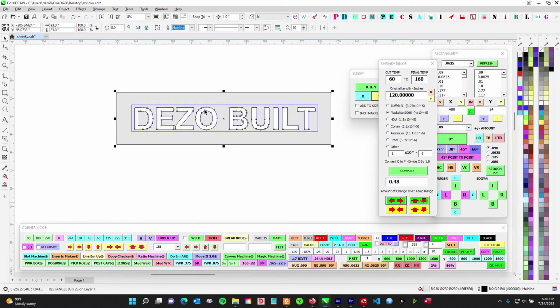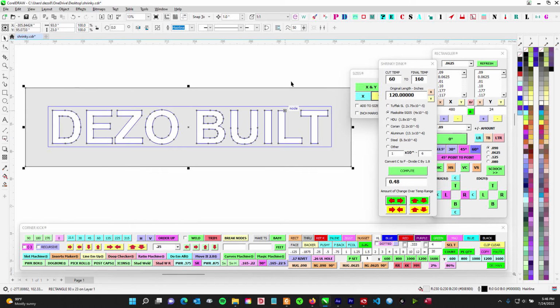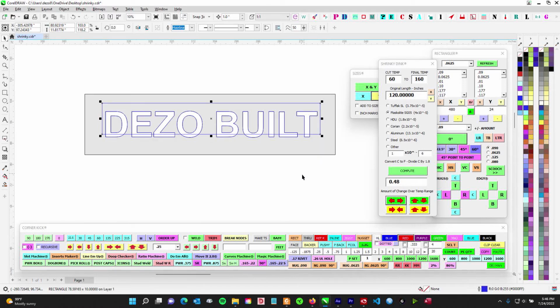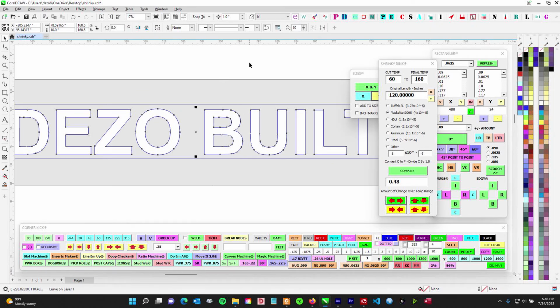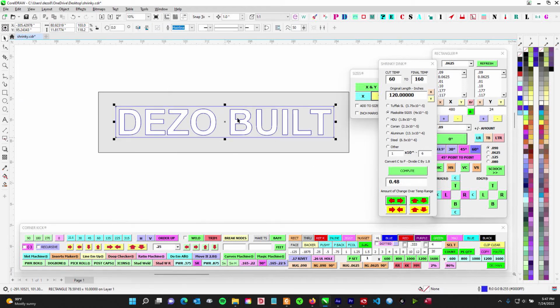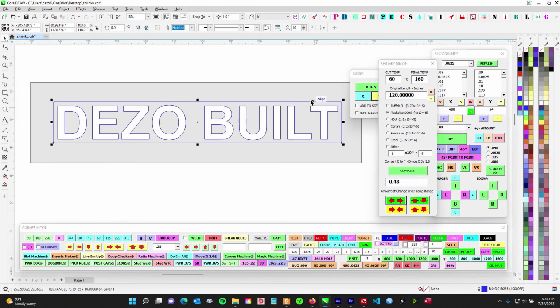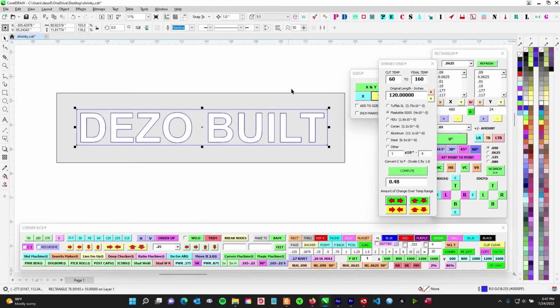So we have a sign frame here, or a sign face that's 93 by 23, fine. We have some 10-inch tall push-throughs. A lot of companies will just route it clean through, put the push-through in, and then they'll take a piece of acrylic and they will just glue, using Weld-On or 7000 series, and they'll just glue that backer on there, and that makes a one-piece kind of unit with the letters. That works great, and then they'll silicone this on. That works great because we use studs and all that, but some companies do it this way.